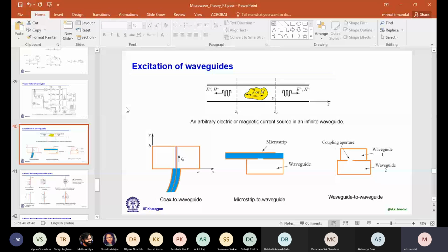So that was for the resonator. Now here, in general, we are going to design some adapters. Let's say with a VNA you have coaxial cables, but you are going to measure a component designed in rectangular waveguide technology. So obviously port 1 and port 2 of your device are rectangular waveguide sections. Then you can't directly connect a rectangular waveguide to a coaxial cable. So for that you need an adapter.